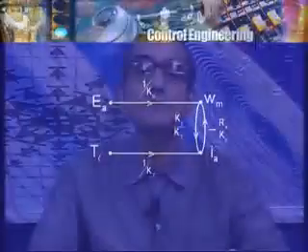The other equation is the torque equation, and what is the torque equation? Once again, the torque produced by the motor, Kt into Ia, equals the load torque plus the torque to overcome friction, and solving it for Ia, that was easy. We get Ia equal to 1 by Kt into TL plus Kf by Kt into omega m, and therefore on the signal flow graph now I can put two more edges to stand for this equation.